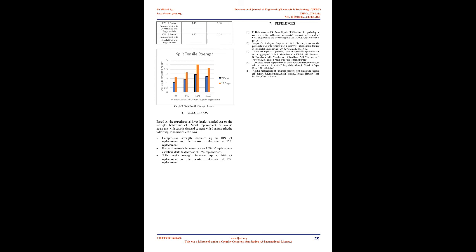Compression test. The compressive strength of concrete, i.e., ultimate strength of concrete, is defined as the load which causes failure of the specimen divided by the area of the cross-section in the uni-axial compression, under a given rate of loading. To avoid large variation in the result of compression test, great care is taken during the casting of the specimens and loading as well. The test results conducted for 28 days are tabulated below.